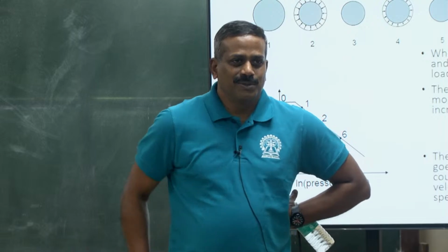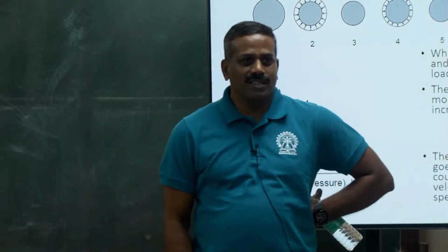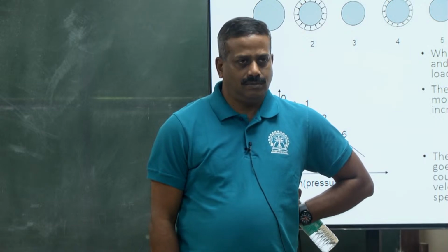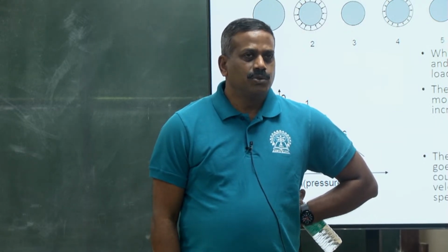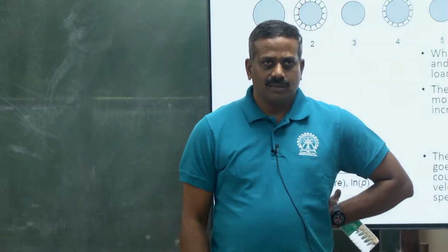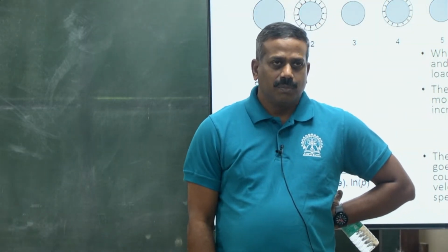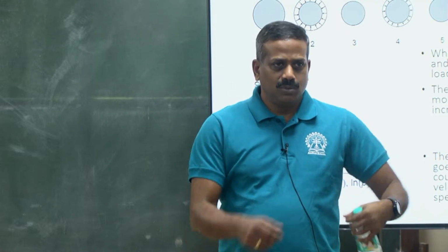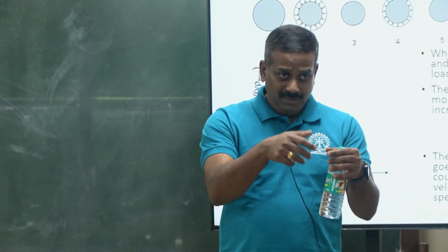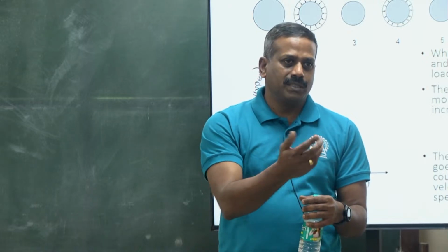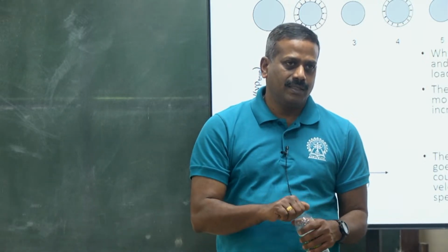Okay. So yeah, we'll come back to your question. Aerated bulk density. Can we use it for air classification? Usually not. The purpose of aerated bulk density is just to break the individual particle bonds and make the particles individual when they flow into the cup during measuring bulk density, right?